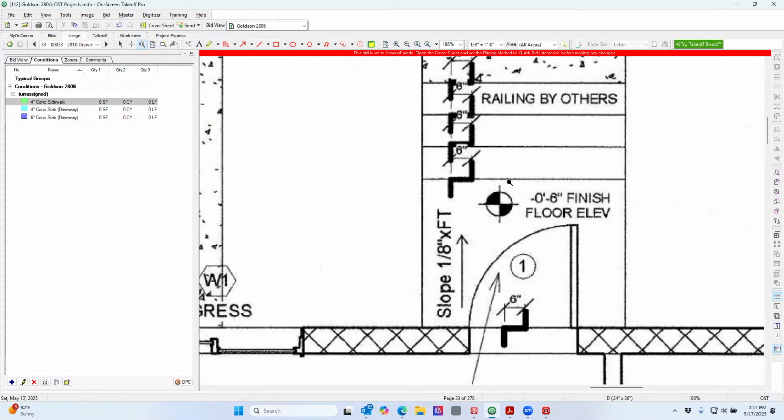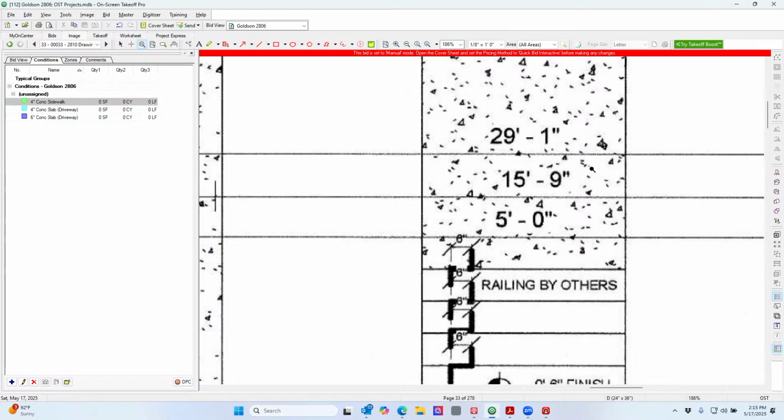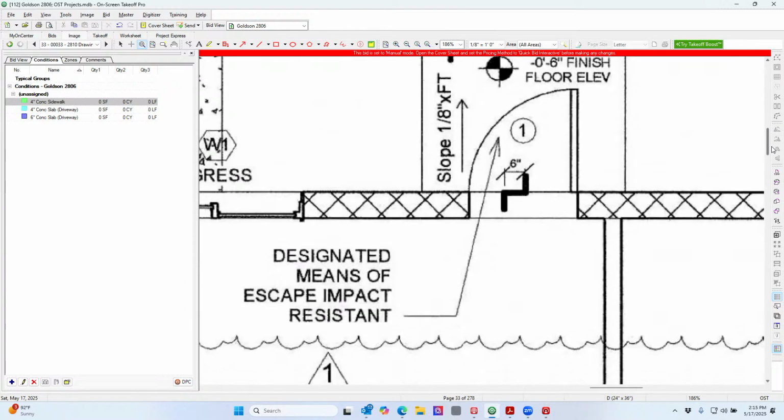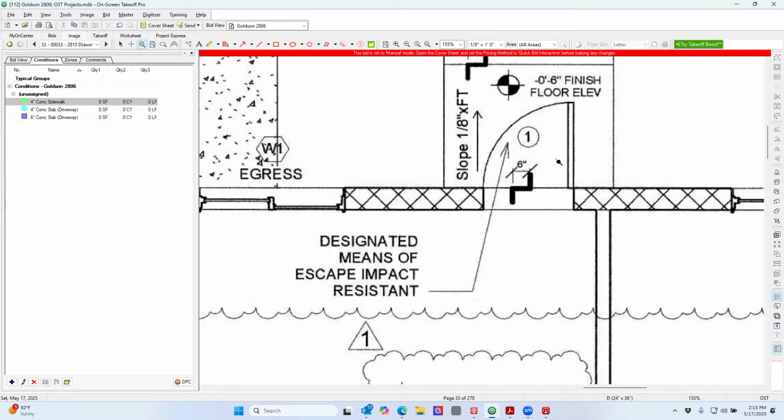Then you have another 6 inches, so when you get here, you're a foot lower. Another 6, another 6, that's 2. So you're 2.5 feet down to the top of the sidewalk already. Let's say the sidewalk is at grade, meaning it's level. We know that we have to raise this pad up at least 2 feet. Let's say it's a 4-inch slab, so 2 feet 2 inches. That means the top of the dirt is 2 feet 2 inches above this ground elevation at a minimum. And that's without having the details, but these are just tools we're picking up by looking at the drawings.